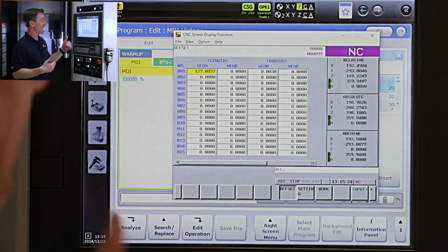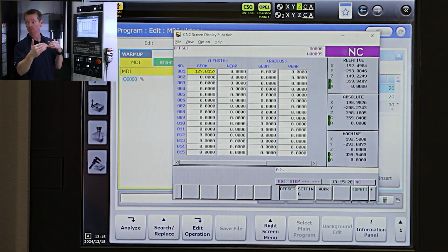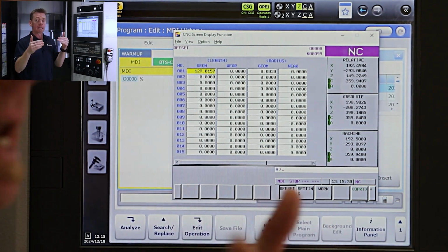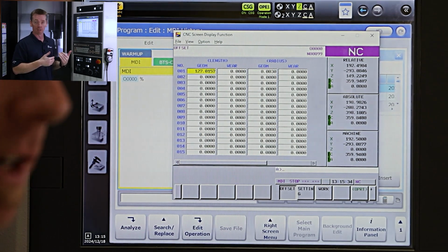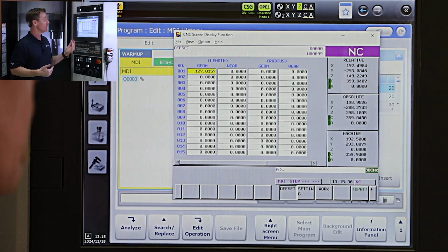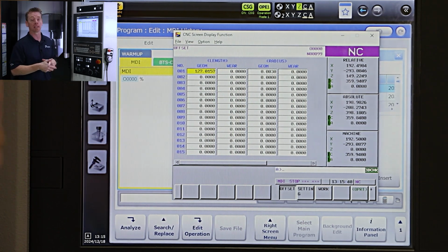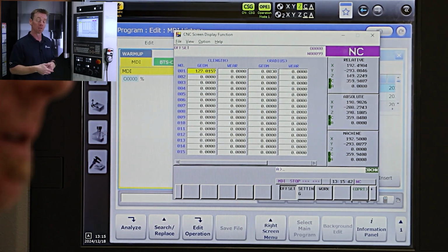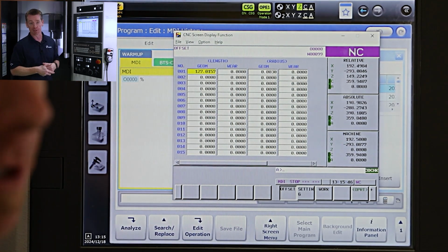There's nothing special that has to happen. You can do one cutting path with the original cutter, the cutter number 1. At any point, we can do an M451 with an S value to move to a different cutter number, giving us different values. One benefit of this as well is if you're using spindle load monitoring, it will actually allow you to use different spindle load upper values as well or lower for the different cutting edges, which could be helpful.